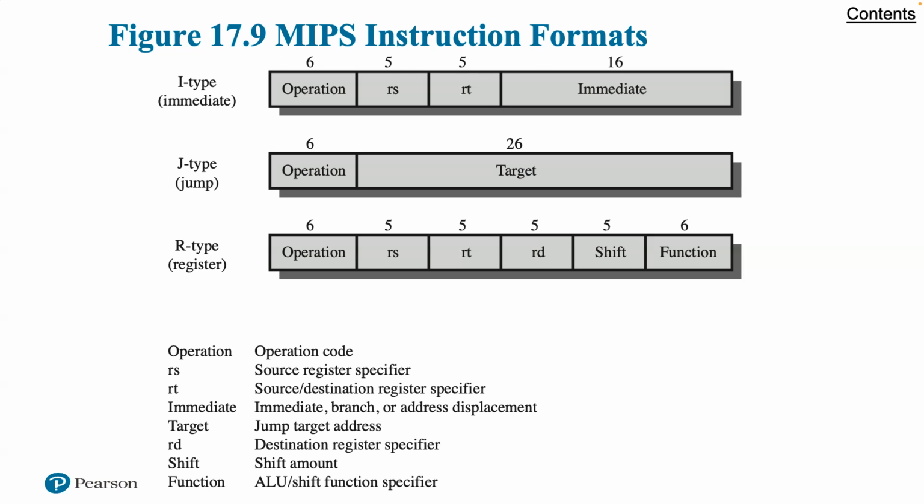As with most RISC-based machines, the MIPS uses a single 32-bit instruction length. The single instruction length simplifies instruction fetch and decode. It also simplifies the interaction of the instruction fetch with the virtual memory management unit. That is, the instructions do not cross word or page boundaries. The three instruction formats, shown here in figure 17.9, share the common formatting of opcodes and register references, simplifying instruction decode. The effects of more complex instructions can be synthesized at compile time.